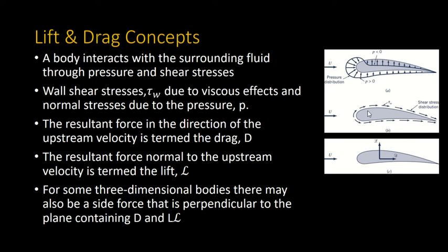And not only pressure, as I mentioned before, we also have shear stress that is distributed around your airfoil. By integrating the pressure force and shear force, we come up with the drag, which is parallel with the incoming velocity, and lift, which is always perpendicular to the incoming velocity U. This is for a two-dimensional body, drag and lift.